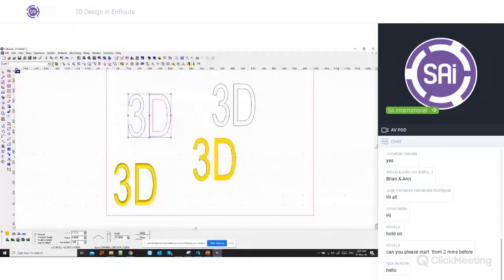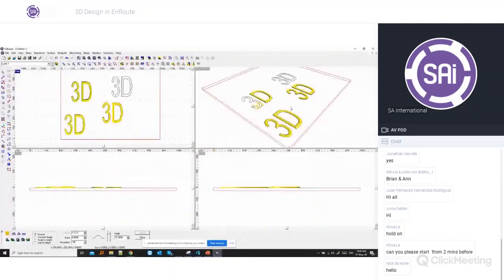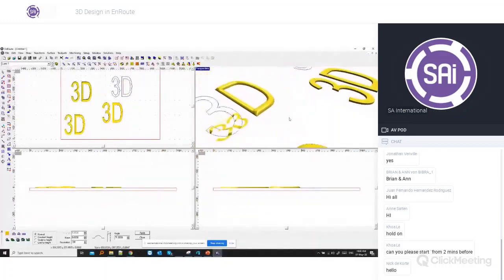Typically, for most applications, a resolution of 100 will be enough. But if you're working with very small parts, you may have to increase the resolution for accurate tool pathing. So if we apply the angle of 71 to the relief, you will see that the height in here will be a bit higher than before.